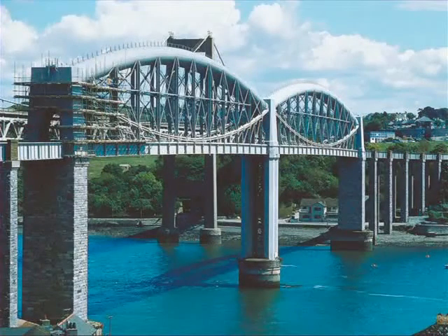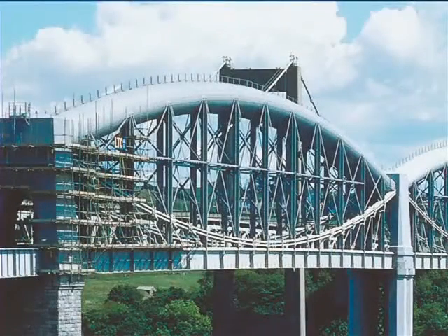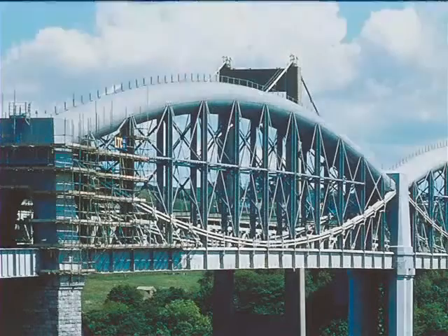We can see this phenomenon manifested in many great structures. In Brunel's Royal Albert Bridge, for example, the magnitude of the compression force in those top chords is about the same as the magnitude of the tension force in the bottom chords. Yet the top chords are huge iron tubes, while the bottom chords are visibly lighter eye-bar chains.